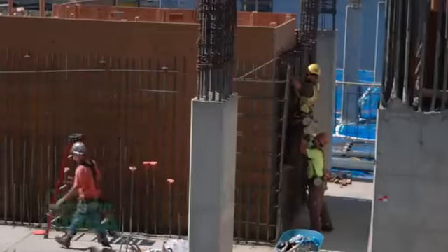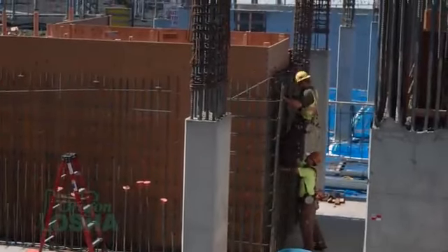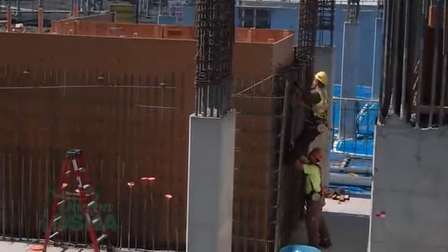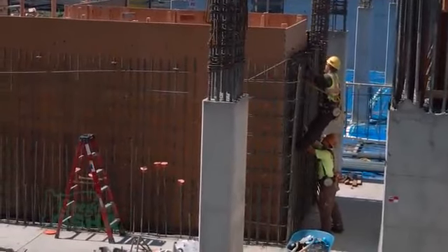When I need to work on a ladder, rebar cage, column, any place where I'm climbing, and I need to take both my hands off to get the job done, I no longer have 3 points of contact. So a positioning device is something I can connect that allows me to connect to my structure and maintain that third point of contact. I can lean back into that positioning device, work hands-free, and still maintain 3 points of contact.